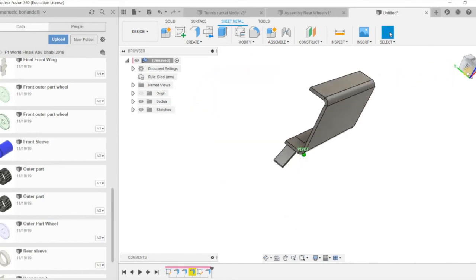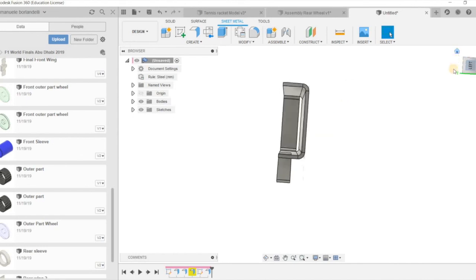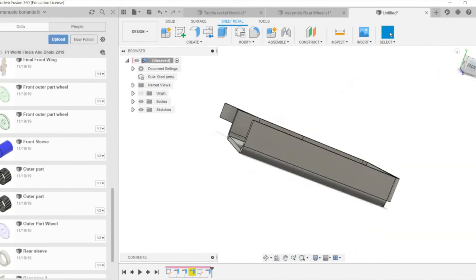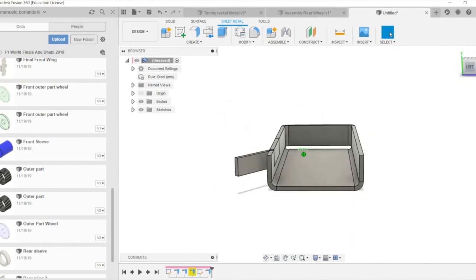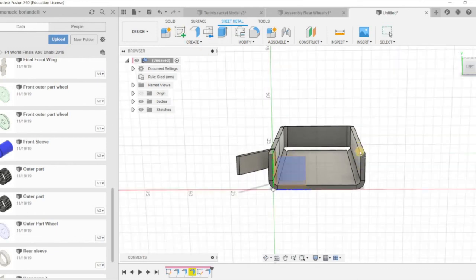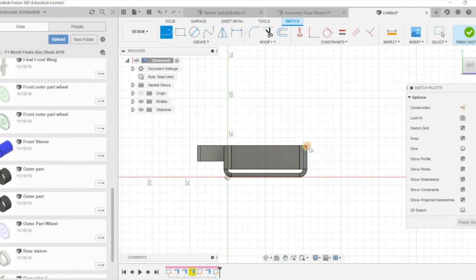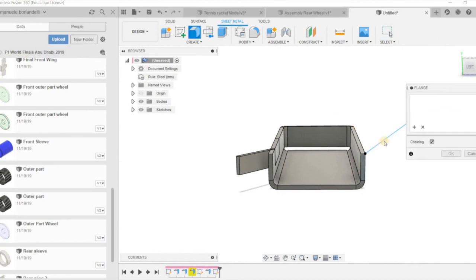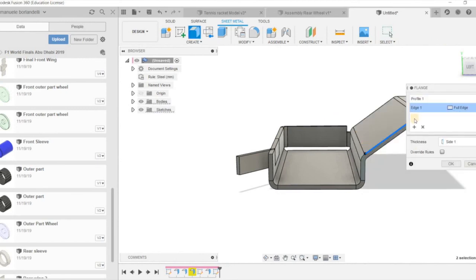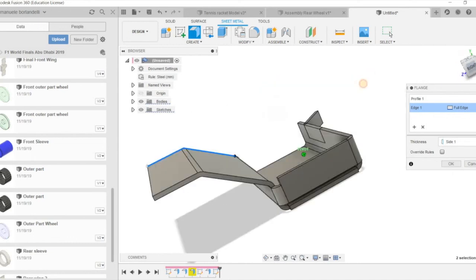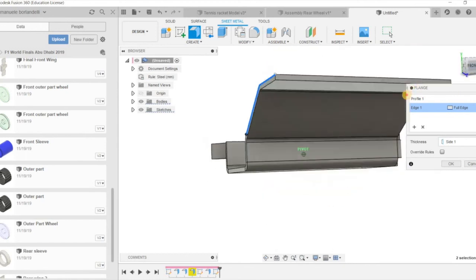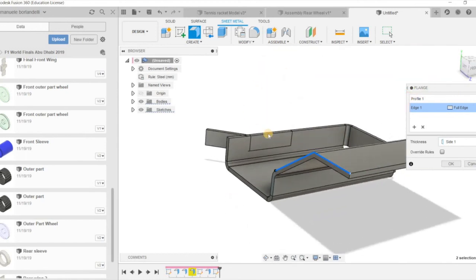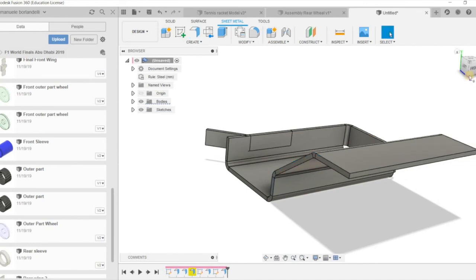Another thing we could also do is, from the side view exactly, I can also create another sketch here, and then for instance do from here and here. I finish the sketch, and then with the flange I can just click on both edges, it creates another flange, which is very useful to save time sometimes. Obviously I can move it, and yeah, so obviously you can move around.